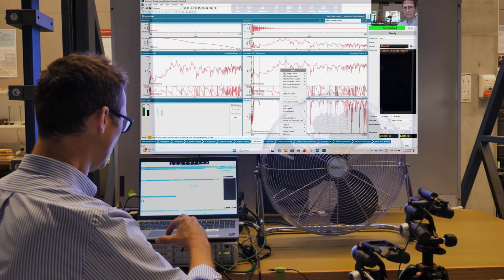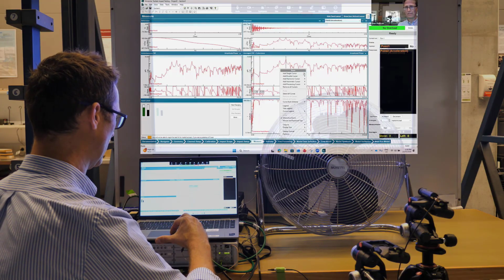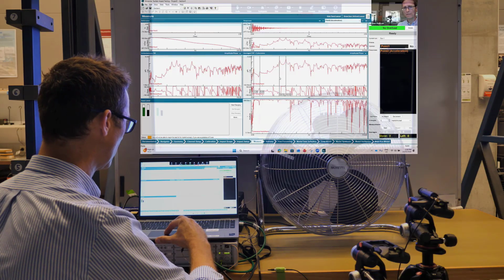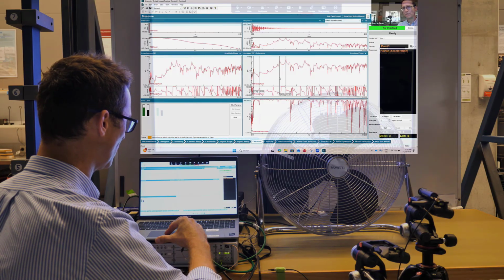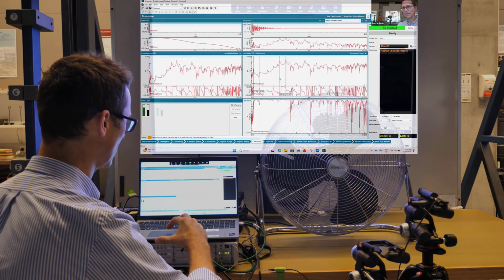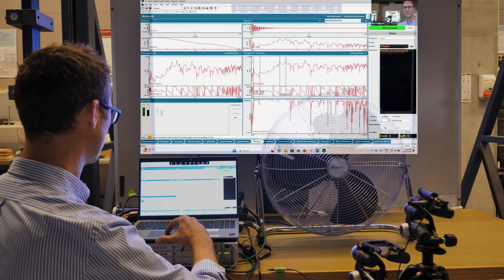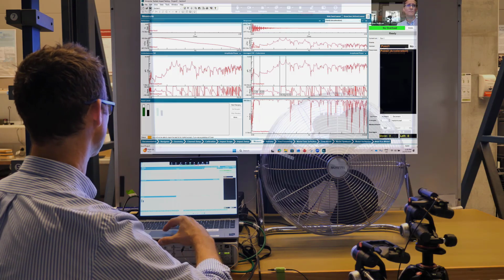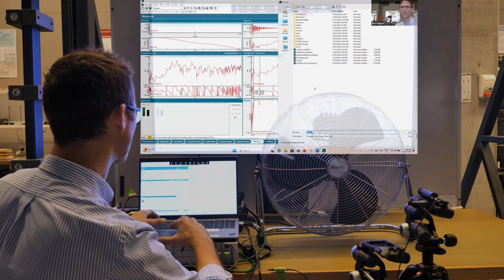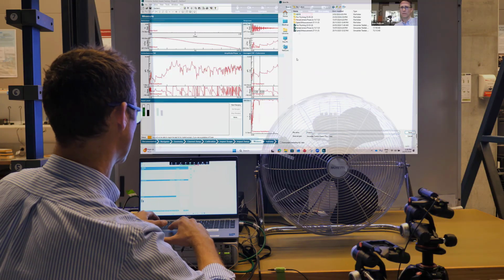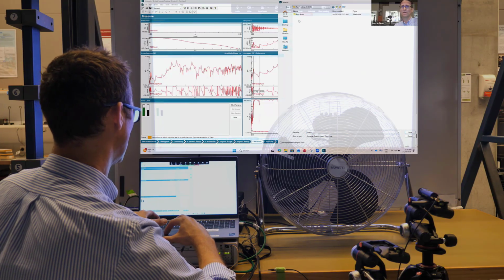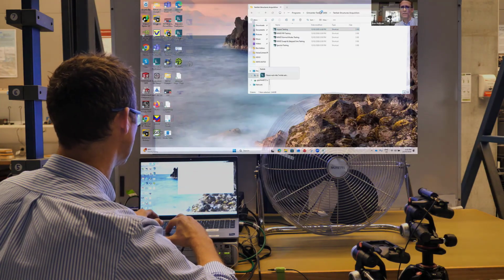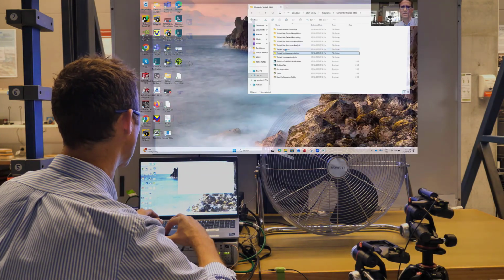There's another one surely in there that I can put on with another cursor. As the forcing function coincides with these structural resonances, then I clearly get more vibration as a result of that, what we would refer to as hitting a resonant frequency. So I'll just close that workbook.